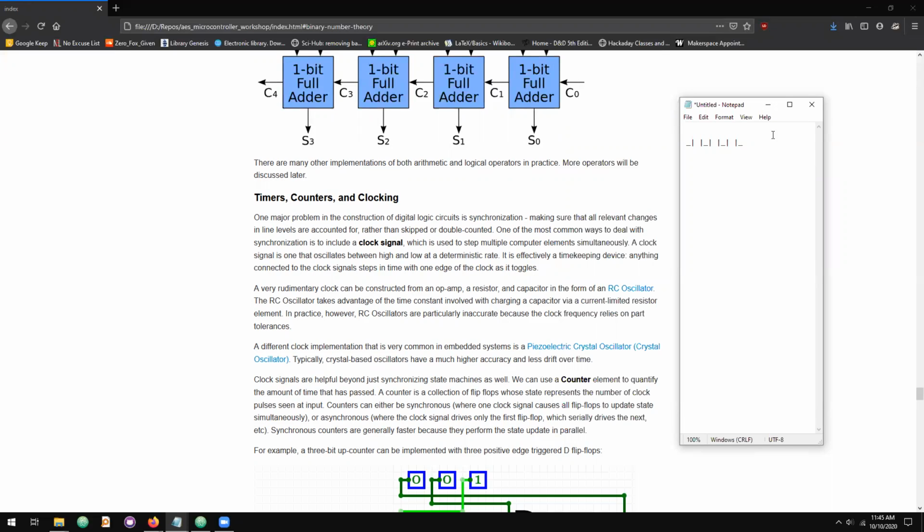There are a couple ways that we can actually produce this signal, though. Before we even get into transistors and special dedicated elements, we can actually use resistors and capacitors to produce a clock signal. It'll be ugly, and it'll need to be signal conditioned so that we only get values logic low and logic high. But it is possible to get an oscillation out of a resistor capacitor pair. And we use the resistor capacitor values to set the frequency of this oscillation. And then, as I mentioned, we do some signal conditioning.